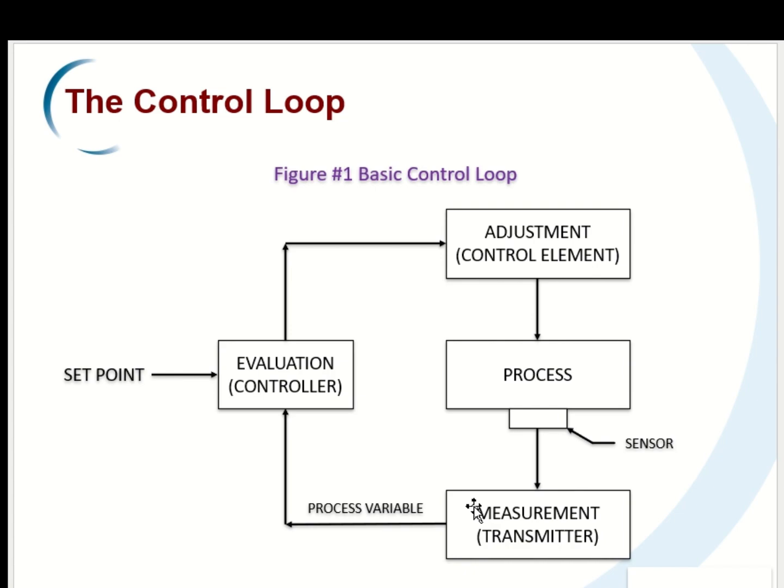The controller produces an output signal to initiate a corrective action on the manipulated variable to bring the control variable closer to the desired value, which is the set point. So you can see the set point is given to the controller, and accordingly it is adjusting to give us the optimal value. So this is the control loop diagram.